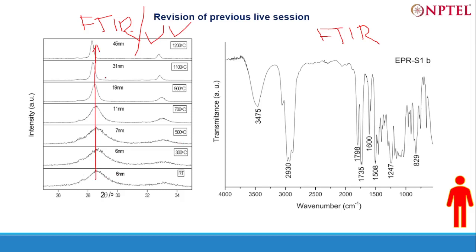These peaks show grain growth. And another thing is that there was no peak here, but as the temperature is increased, a peak is seen for the first time at 700 degrees Celsius, then it grows and grows. So you can say that at 700 degrees Celsius, new peak growth is identified.